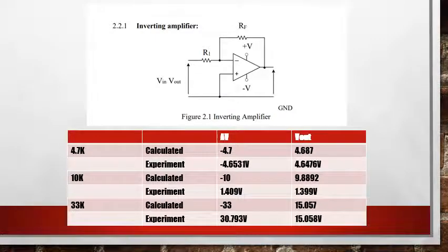So here is a basic circuit diagram of an inverting amplifier. The signal is applied to the inverting input, which is represented by pin 2, and so the output will have the inverted signal. RF is known as the feedback resistor. This resistor takes some of the output signal and feeds it back to the input. As a result, it reduces the voltage gain. Now when you have a feedback resistor, the voltage gain is said to be a closed loop voltage gain, and that gain is equal to RF divided by R1.